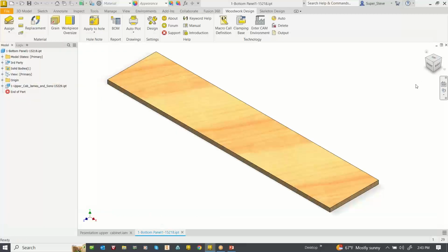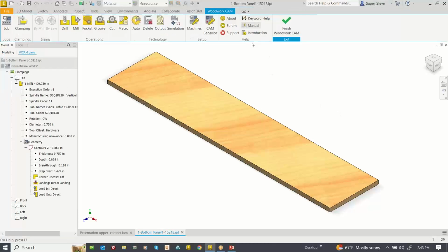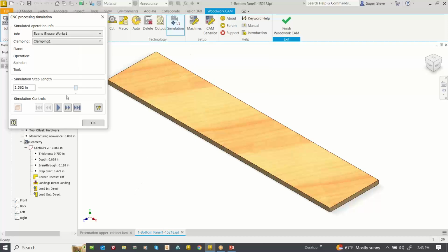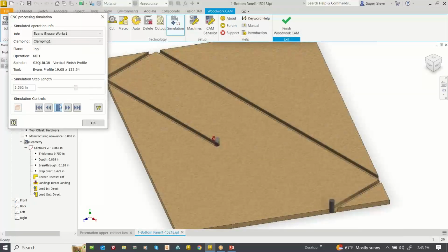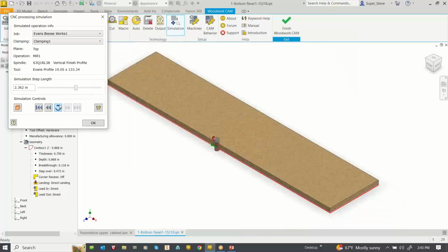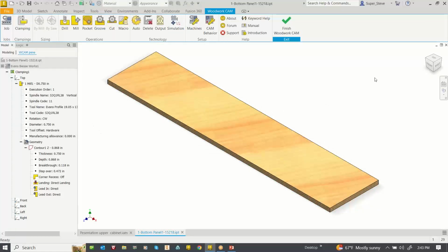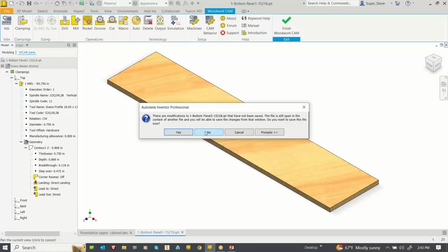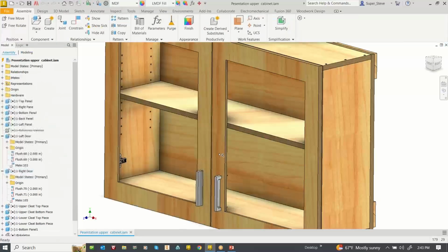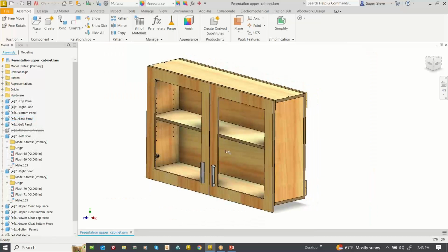So what does that mean? Well, if I now picked auto and I went to simulate it, it's a little different. Notice it's cutting it on a 60-degree angle. And again, because it's MDF, it's maple on MDF, it is showing you that with or without the veneer, this is what would happen and the grain would actually show correctly. So just really simple things like this are done automatically. And it's more towards what a user would consider to begin with.